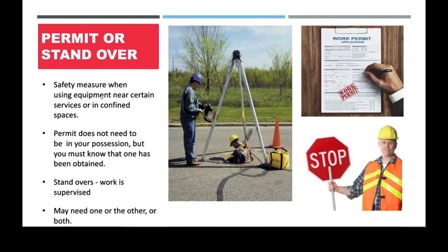So also part of that is planning the job out carefully, how you're going to do it, how you're going to avoid damaging the services. So usually you would identify the services first. So someone would mark on the ground where the services are. You would use your machine, and then within like a meter of the service, you'd stop using the machine and hand dig around those services in a safer way.